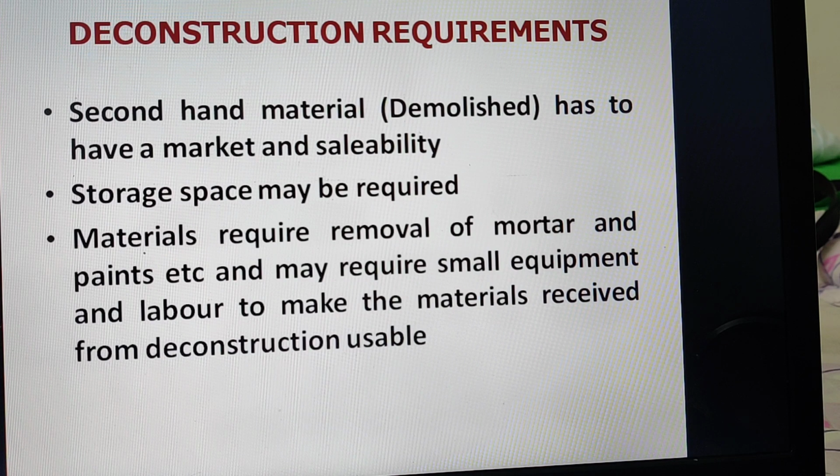Deconstruction requirements: the second hand materials have to have a market and sellability, because it is important. Whatever reusable materials are obtained from this technique should have a market and sellability. Then storage space is required, because they are to be stored somewhere until they are used or sold. Then the materials require removal of mortar and paints, etc., as they stick to the primary materials, and may require small equipment and labor to make the materials received from deconstruction usable.